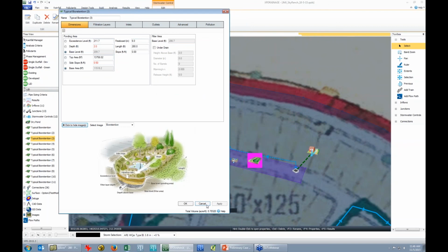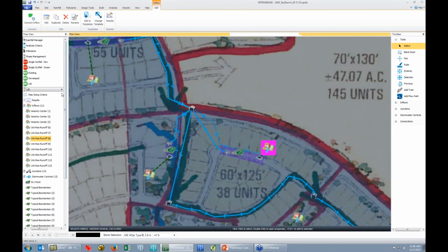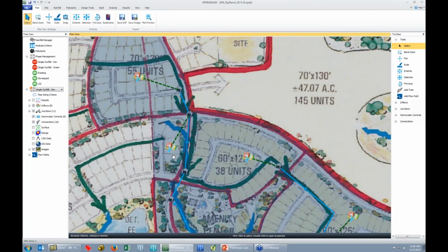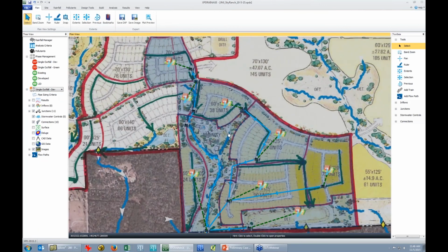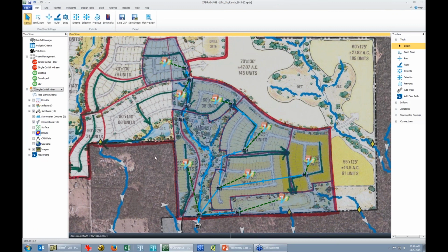Rain garden. We have flow into this rain garden, and there's a high flow bypass for the higher events, bypassed out into this manhole vault and into the collection system. Something I can show, I might just jump to the very early developed scenario. So here's a plan of the site layout. You can see how early it is. There are even marker arrows showing where the flow is going to move. You can incorporate the surface, and that's how we delineate some of these catchments.